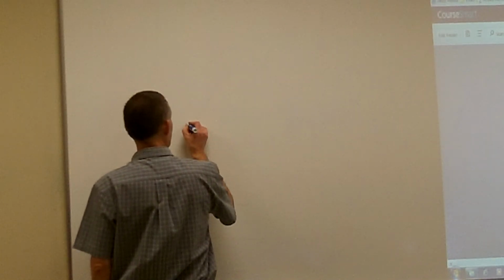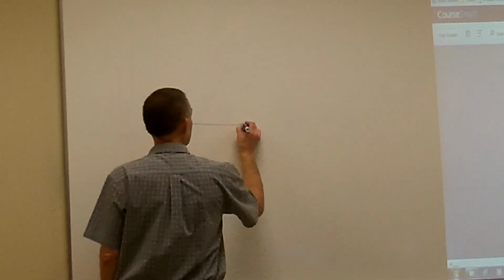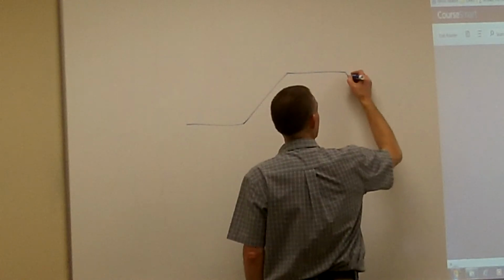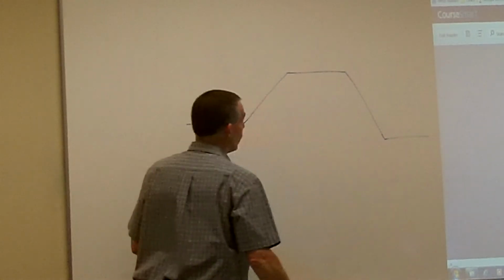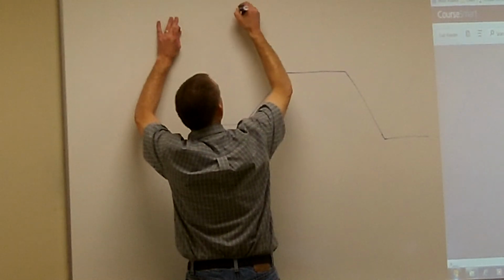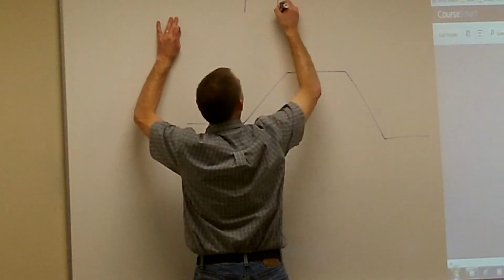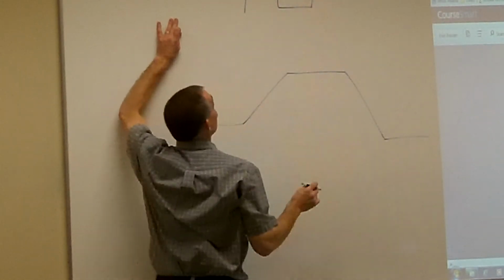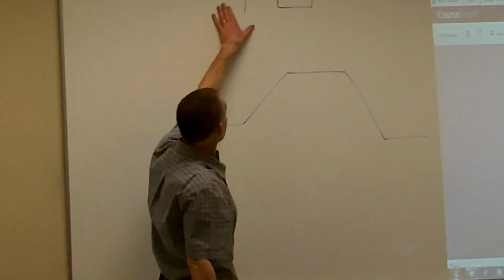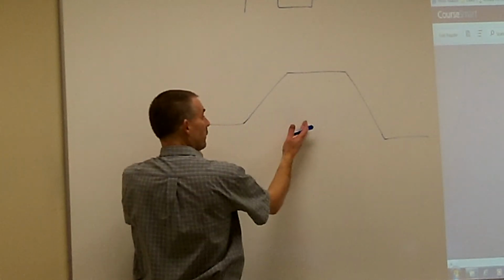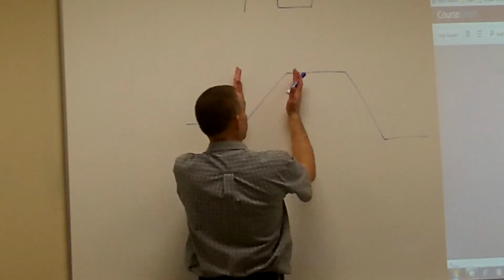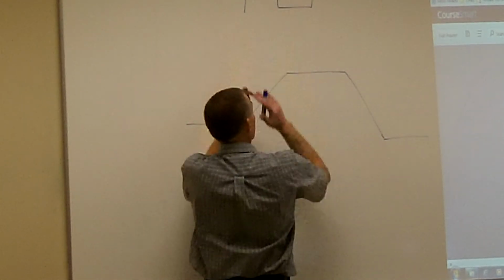I'm going to zoom in on one pulse width. So what I'm saying is, it's going to go low, then it's going to go high. So that's what it actually looks like. If I look on the oscilloscope, and if I have my time set to a very long length of time, it just looks like a nice perfect square wave. But if I really zoom in on my time, narrow it down and make it really quick, then I can see that I actually have a rise and a fall on this same signal.